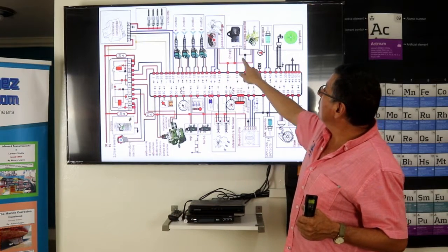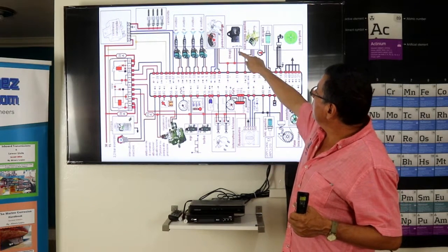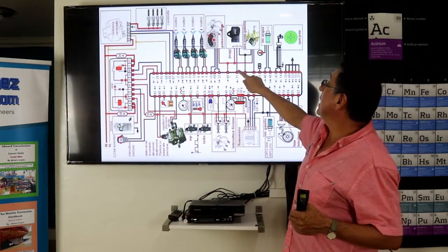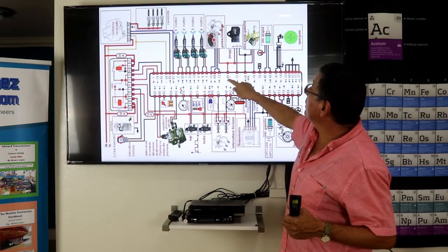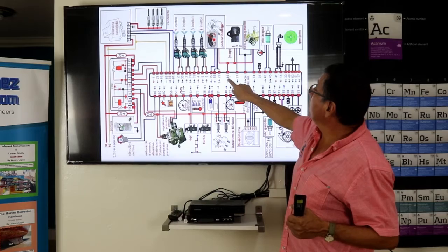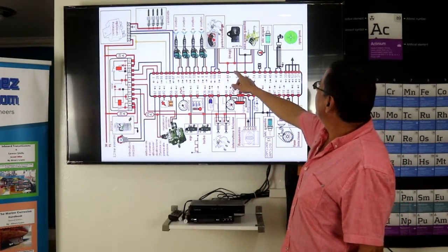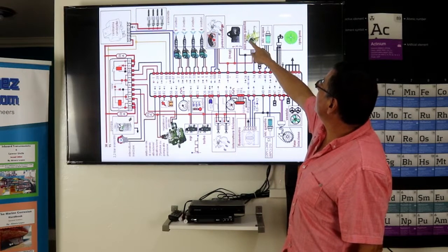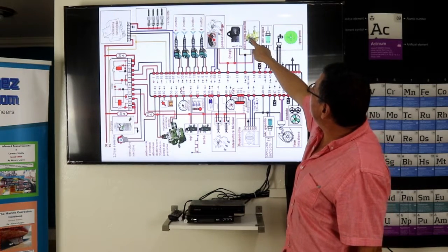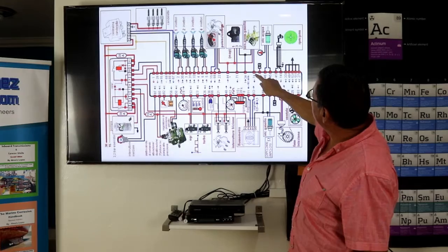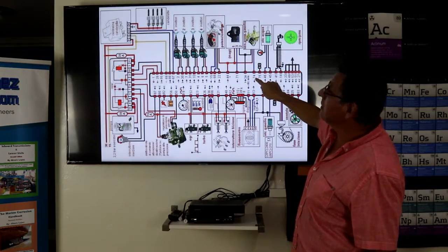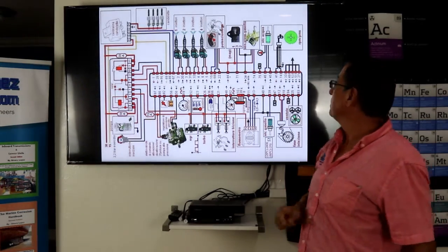And the pins are one pin ground, another pin signal, pin 71, and another pin constant power coming from the computer, 12 volts, coming from pin 44. Marvelous. And the other one, the pressure regulator at the common rail. The pressure regulator signal is coming from pin number 74.